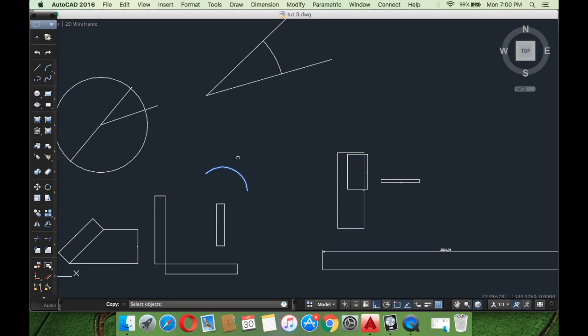The cursor appears, you select the object that you want to copy, you right click on it, select the reference point, and you place it there. You can do it this way as well. Each and every command can be executed with the help of the command line. If you are working professionally, then the command line is a very important aspect that you'll have to keep in mind, because professionally you'll have to work pretty fast. So we come to rotation then.